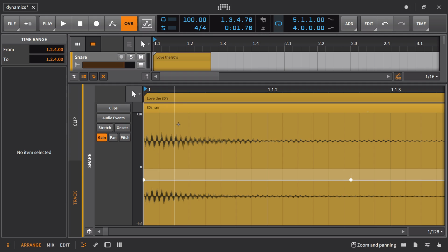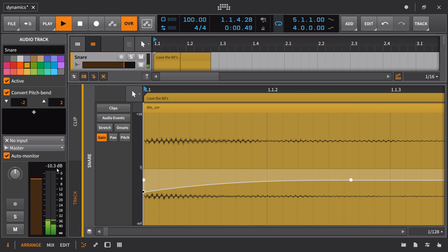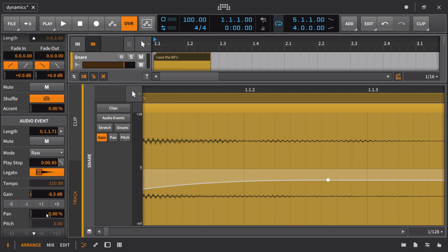Okay, so in this example, let's say that we want to reduce the peak level here. I would just go right from the very beginning, super fast attack time, bring that signal down, and then have it come back up. That's what the release time is saying, to the original point. So now when we listen to it, it's just going to sound a lot quieter than it did before. And if we take a look at the peak value, it has been brought down by roughly 4 dB. So now I could come in here and bring 4 back into it.